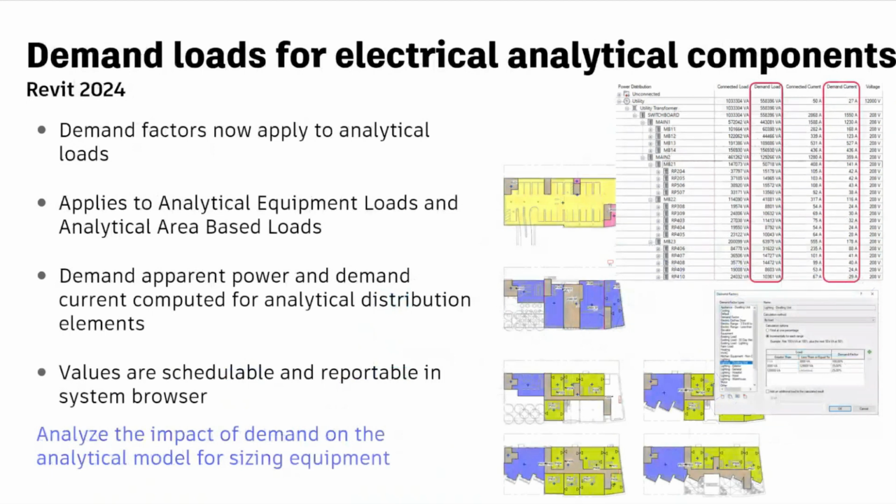For electrical loads, demand factors now apply to the analytical loads. Demand loads and demand currents are now calculated for each electrical analytical component and displayed in the system browser. For each load classification, the total connected and demand load is schedulable in units of power and current.